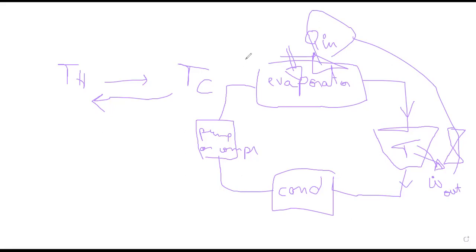So this is why, to operate this cycle in a continuous way, after the fluid gets out from the turbine, it is now at a lower energy state, but we need to repeat, and in order to be able to repeat the process, we need to bring it back to the state where it entered the evaporator. To do so, we should pass it first through a condenser, as the name indicates here, and the condenser will have rejection of heat. So Q out. And we'll see this in detail when we study the cycles next time.